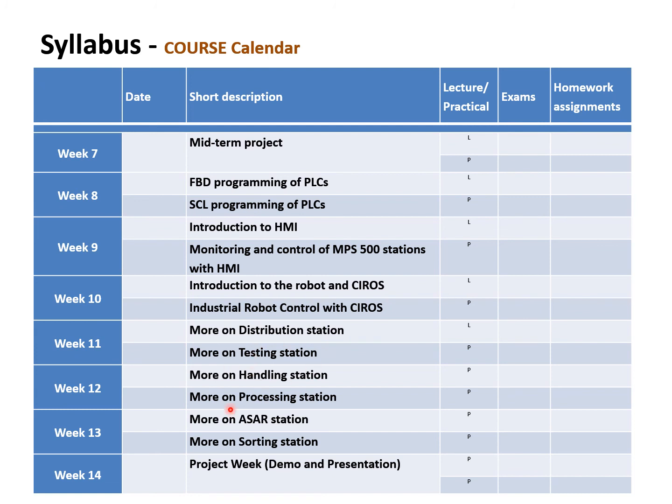Okay, so all of these are projects that students use to program different stations of MPS 500, but we don't have to necessarily stick to these stations. I could either provide you with the electrical and pneumatic circuit, so you have to design it in Festo FluidSIM and program it with either Codesys or TIA, and then connect them together and test your program and pneumatic design.